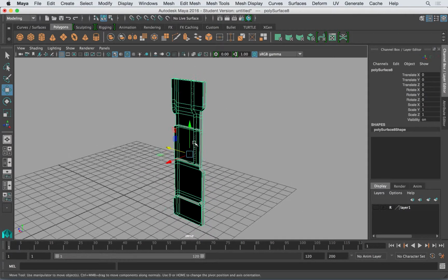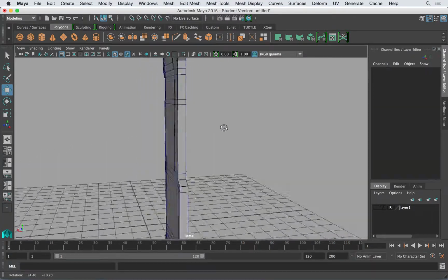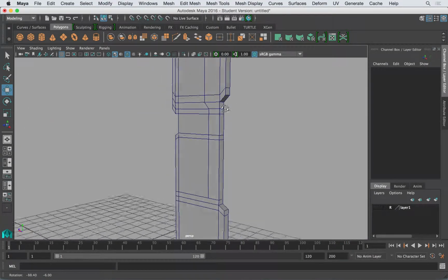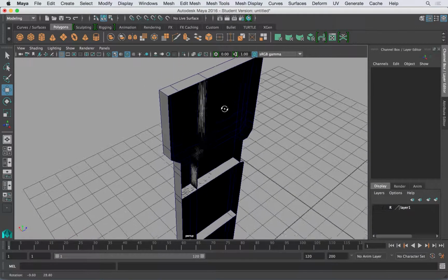So how do we flip it? That's the axis of the flipping that I want to do. So that's the X. Then I go to scale, minus X on the scale, minus what number is there, 1, and that's it. So now it's good. Don't worry about the flickering effects because they're overlapping faces now. So here's what I have.